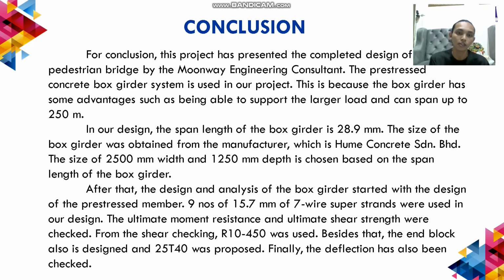In our design, the span length of the box girder is 28.9 meters. The size of the box girder was obtained from the manufacturer, Hume Concrete Berhad. The size of 2500 millimeters width and 1250 millimeters depth is chosen based on the span length of the box girder.